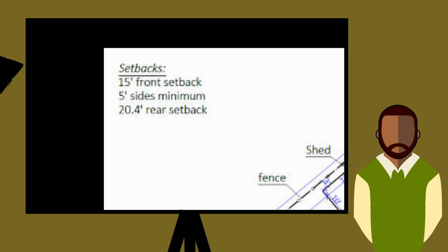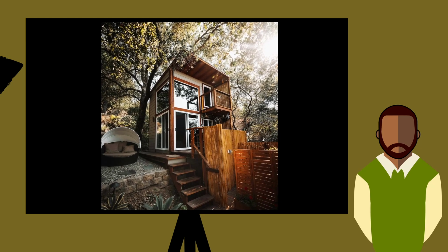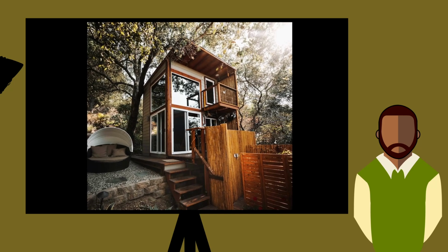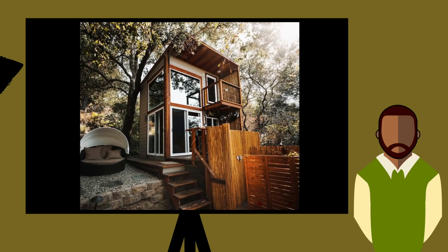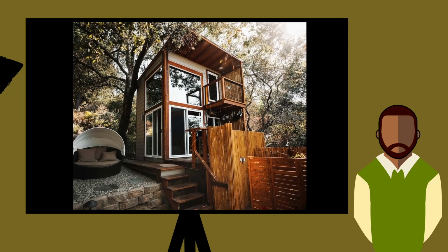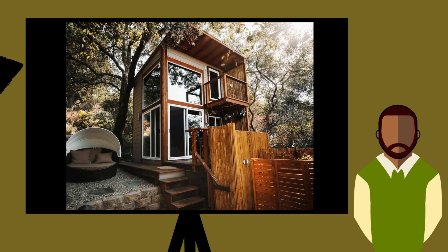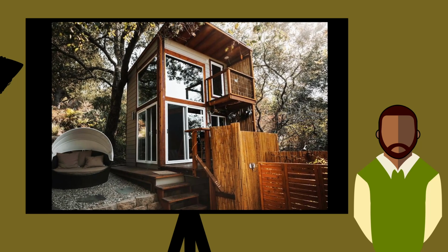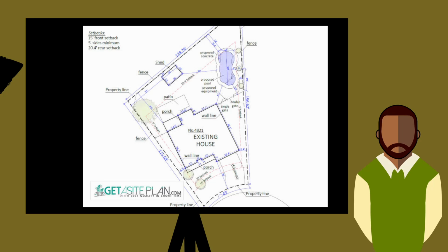Another thing in terms of space is you want to think about this in terms of entry, exit, and privacy, right? Because entry and exit, if there are going to be guests in this particular tiny home, where are they going to park? Are they going to park on the street? Are they going to actually pull up to the space? And where's your driveway going to have to be located if you do have to install a driveway to this space? These are huge questions, and what's that driveway also going to be made of, right? These are things that you need to kind of work out.